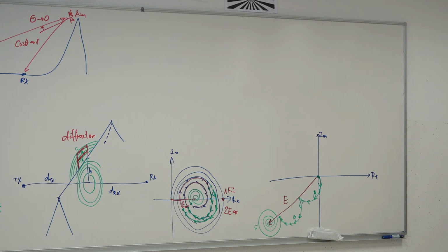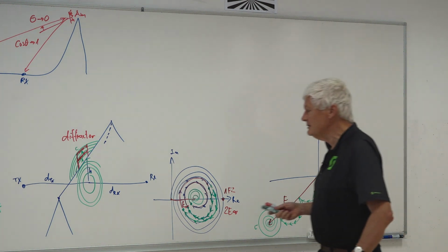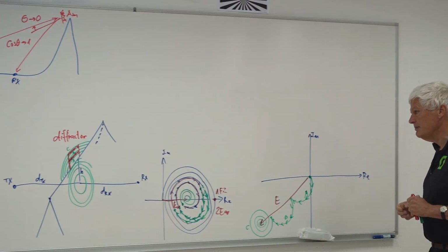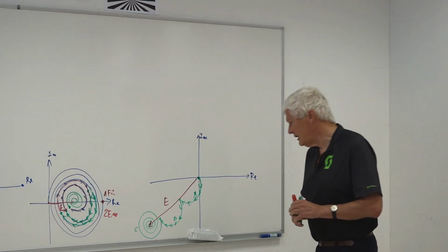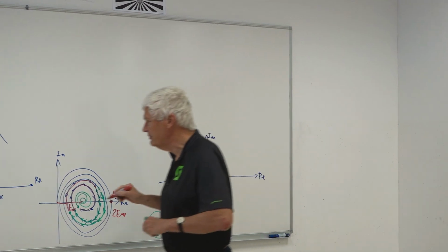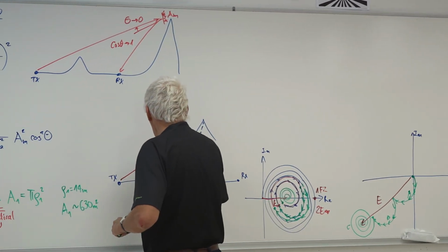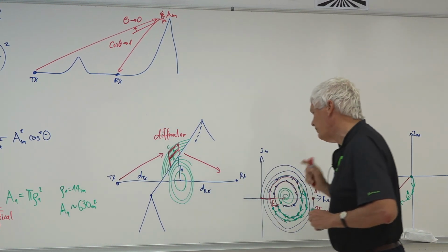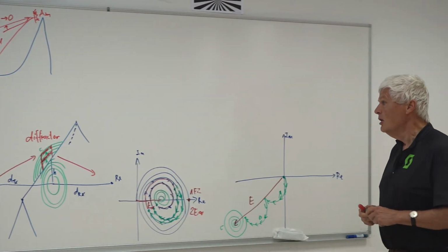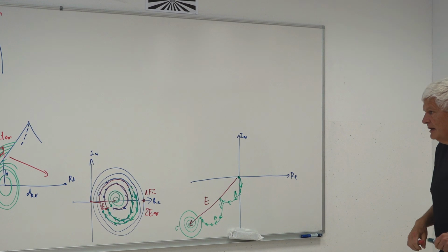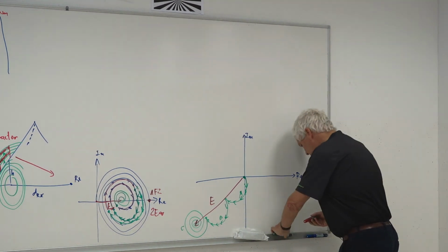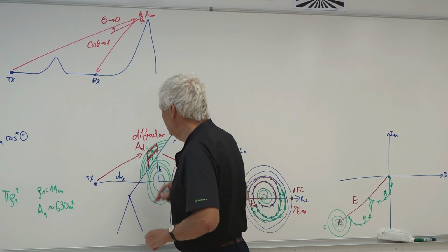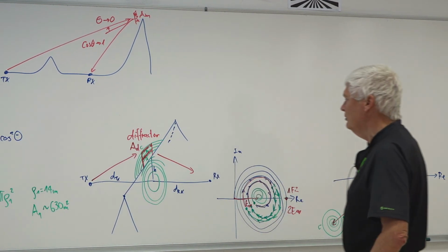So I can remove even Fresnel zones, leave just odd Fresnel zones free, and I have summation with such a diffractor. And this diffractor will actually amplify our field here. What comes from the transmitter will be amplified in the direction of the receiver. Will be focused, not amplified, but focused towards the receiver with the diffractor. What is the calculation for the diffractor? The diffractor has a surface. What is the link calculation right now?